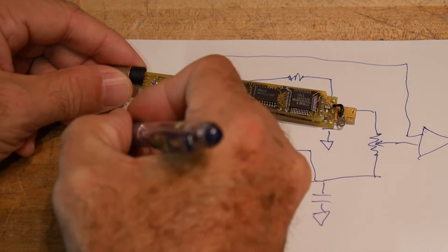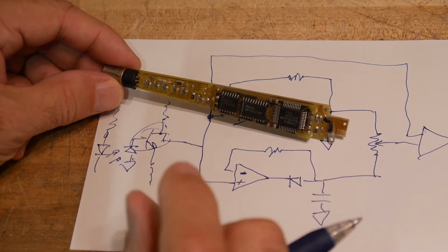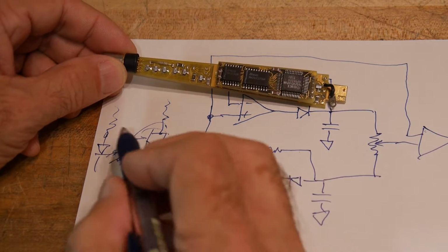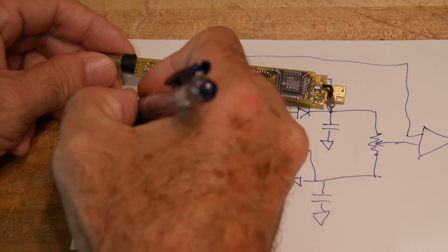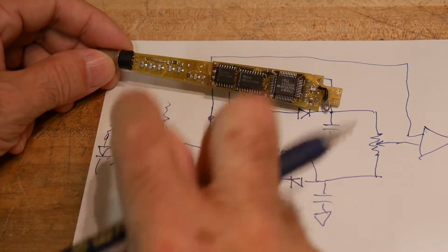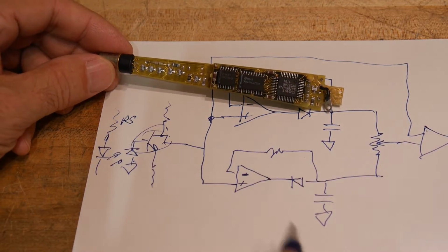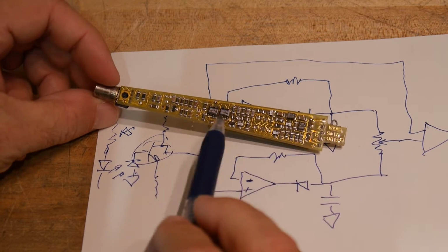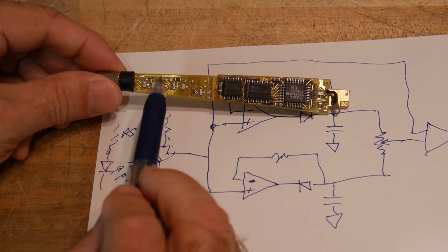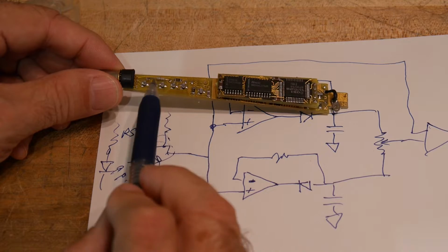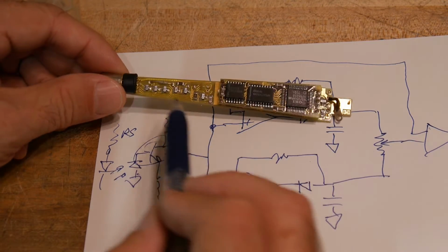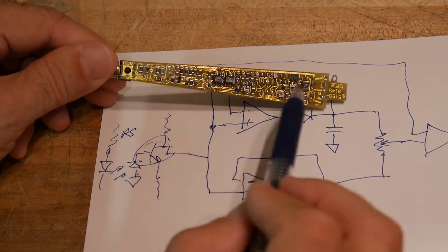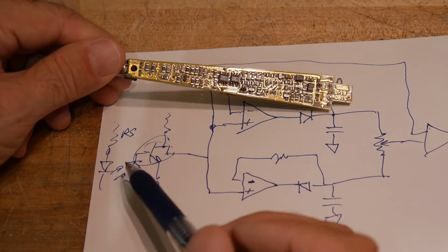Since these things kind of varied a bit, the current through the LED is kind of critical to get this thing working right. Since these are a bit different in gain and everything, you sort of selected this resistor to make sure this all worked really well. So you can see this whole thing is a surface mount, except for this one through-hole resistor right here. And that resistor is this binning resistor where you get to set this thing. So these had to be adjusted in production.